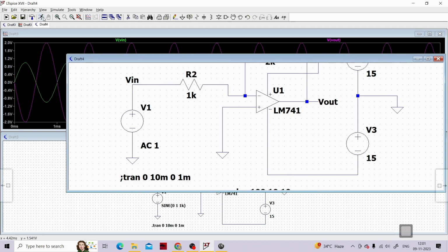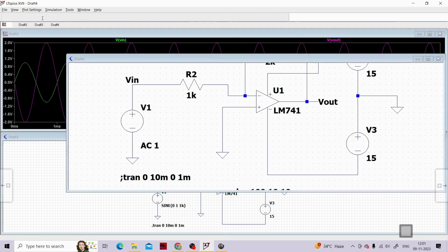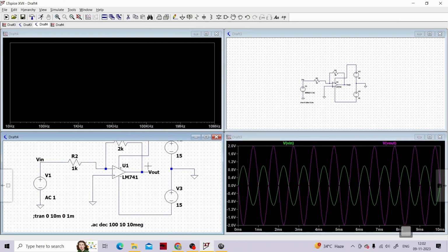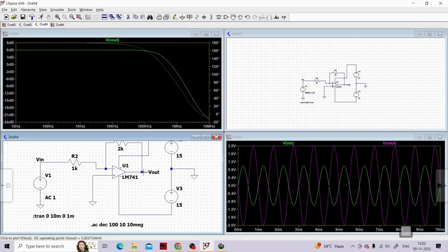And then we just need to run this particular circuit. We want the frequency response at the output side, so we will just click. You see a probe-like symbol appearing, so we click on the output side, and you see we are able to get the frequency response of this circuit. But what we really need to understand is how exactly it is behaving. Forget about what gain we are getting, just look at the frequency response. As of now, we just need to understand whether we are able to get a stable gain at higher frequencies or not. That is the point of our interest.